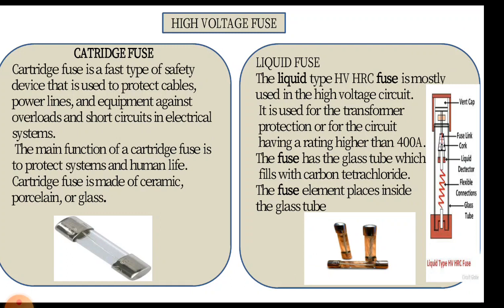The main function is to protect the systems and human life. It is made up of ceramic, porcelain or glass. Then liquid fuse. Liquid type fuse is used in high voltage circuits.